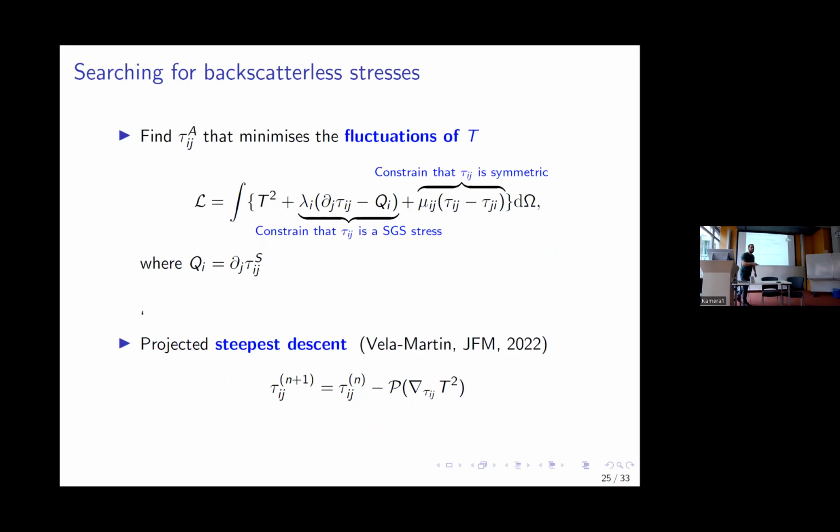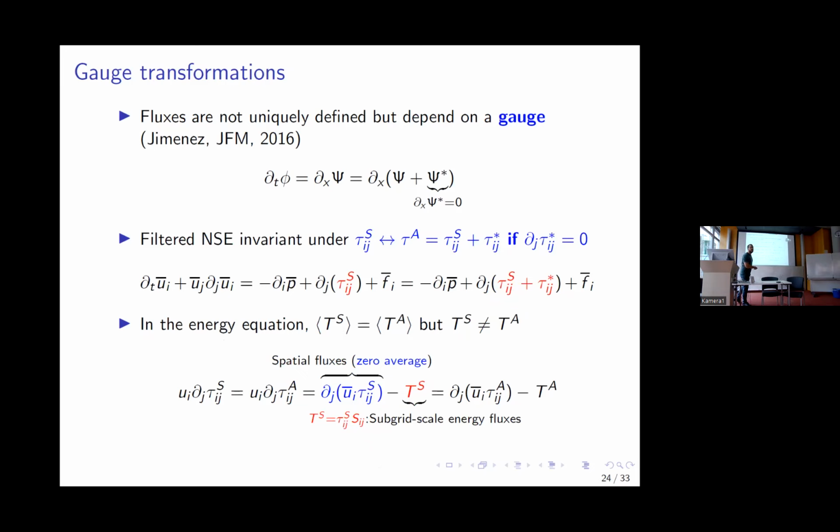Where's the tau star? Where does it show up in the last equation? So it's an alternative. In this one, you mean? Yeah, the tau star. The alternative is already TS times the tau star. This tau alternative is the subgrid scale stress tensor, and the standard ones and the alternative ones are the same as the standard ones plus something that has zero divergence.